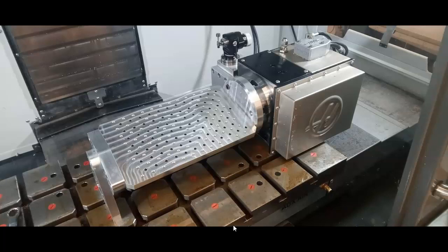If you're not familiar with machining, in a 2.5 axis program, the tool will come to a location, move down in Z, perform some operation in X and Y, and then retract. In 3 axis, if you look at your mouse, the tool would go up and over and follow the contours of that mouse, or make a mold for that mouse.